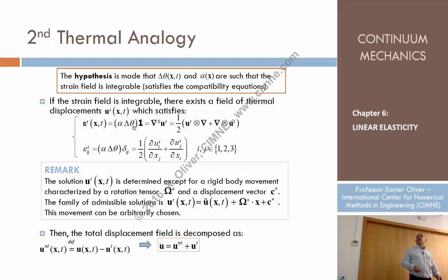These displacements are called thermal displacements, UT, okay? So, okay, we know the strains, which are given, being the symmetric gradient of some displacements termed the thermal displacements, and we have to solve this system of equations. And we know how to solve it. You know that there were two stages, you remember? First stage to know the rotations, second stage to know the displacements. But we also know that it's not always possible to solve the problem.